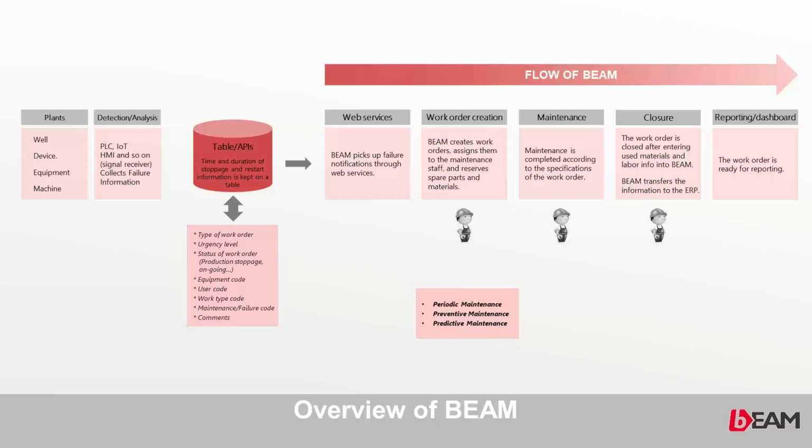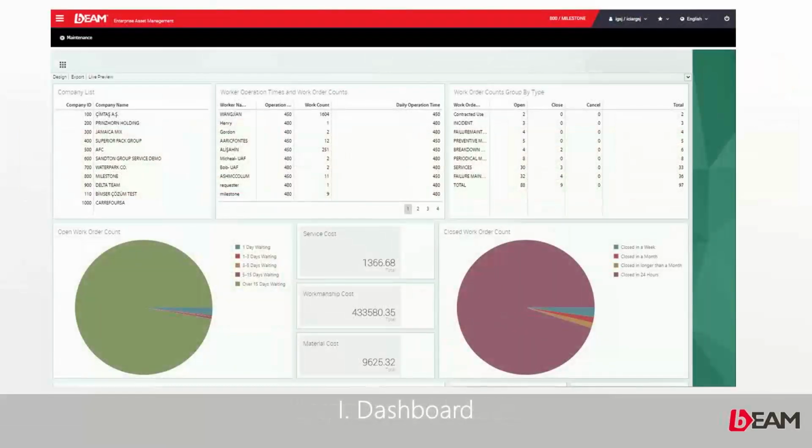That is why companies deploy BIM at their organization, so that you can take care of periodic maintenance and preventive maintenance. But with the help of this type of setup, where BIM is listening to your IoT device or PLC device, we are preparing your company to perform predictive maintenance. Before anything happens, just by symptoms, we take action with the help of BIM so that we can be proactive and you can extend the lifetime of your assets.